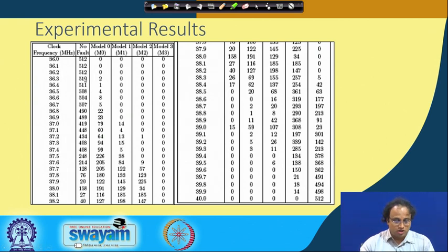When I start increasing the clock frequency, I also get faults in the M1 category, which means more than 1 diagonal is now getting corrupted. Likewise, when I increase the clock frequency further, the fault propagates according to model M2, and when I increase it further still, I get all 4 diagonals corrupted. That means the faults are now according to the model M3.